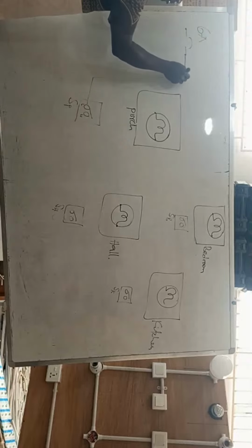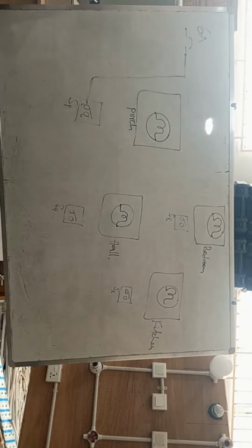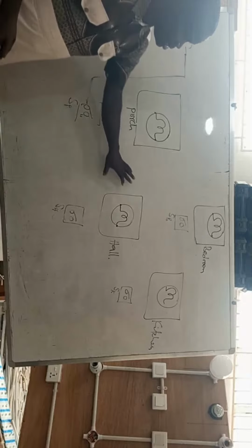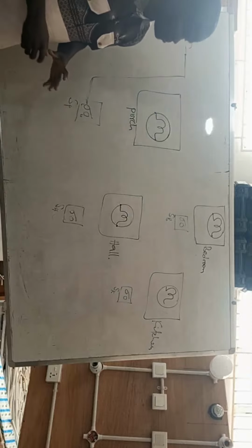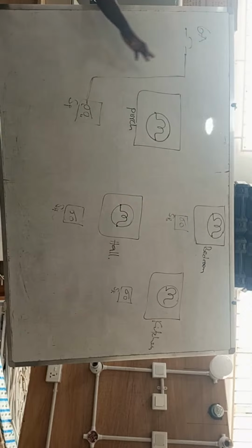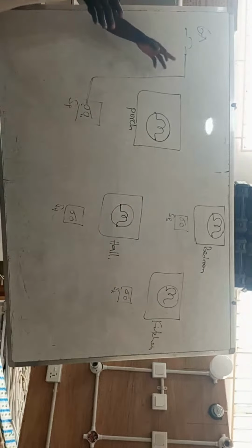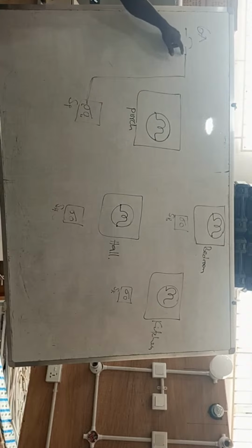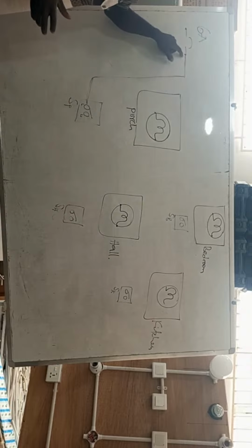Now, because we are controlling each of these lamps separately, each of the switches would have to get a feed that comes from the breaker. But in an installation, in a wiring, we don't necessarily have to pick all the feeds to all the switches from the breaker terminal.